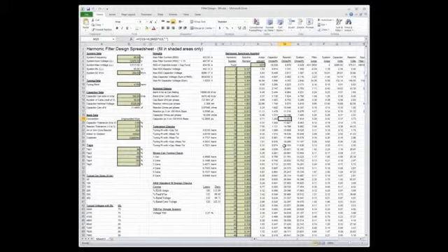And you're going to have to play with the amount of power factor correction that you need versus your first parallel resonant point. Remember, we discussed that the first parallel resonant point changes depending upon how big the size of your capacitor bank is and also what the upstream short circuit impedance is. And so we have to balance those back and forth.